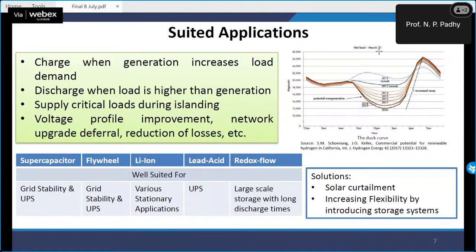It may so happen that if it is a big generator of, let's say, 500 megawatt, then it must go from 10 to 500 in 2 hours time. And that is the challenge associated with the duck curve. And that is what we experience. So having more PV in the system will lead to instability, because the machine I'm calling to generate 500 megawatt in 2 hours, which is next to impossible, ramping is not possible, and the system will lead to collapse in the unstable region. All right.